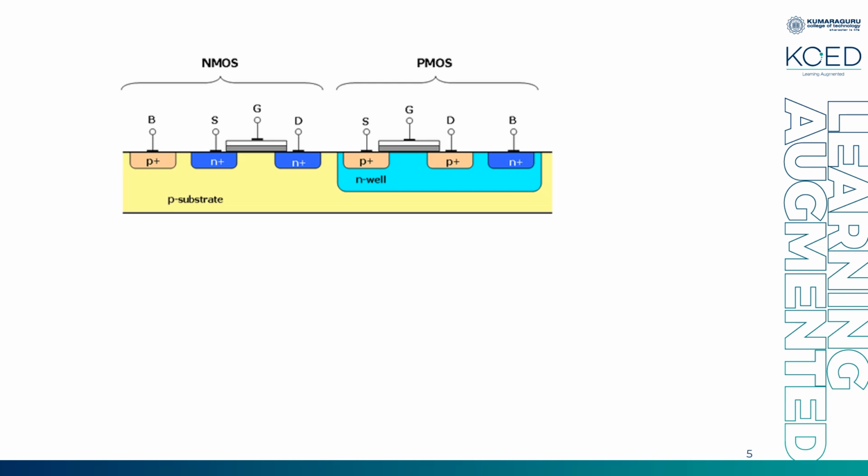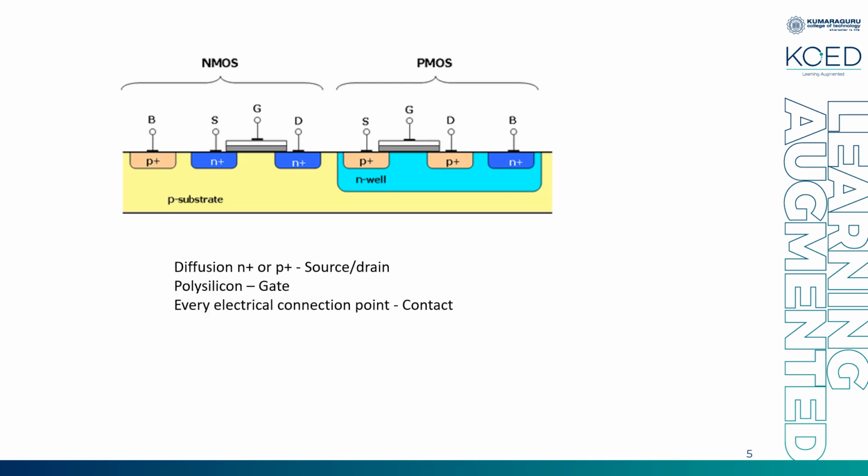This is your basic CMOS circuitry, that is, the basic CMOS circuit is nothing but an inverter. Here you don't refer to anything like source, drain, gate, substrate, body contact. You mention everything with respect to layers. Your source and drain will always be called diffusion or active area.